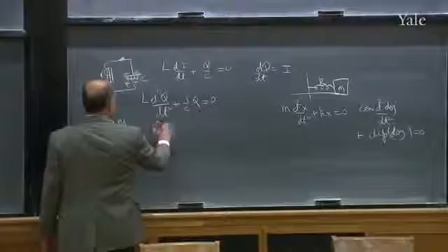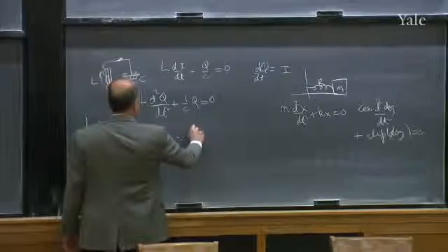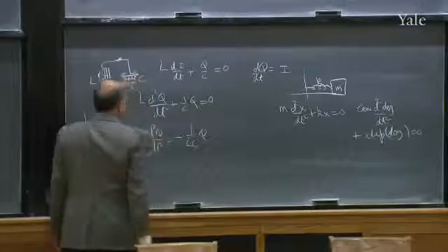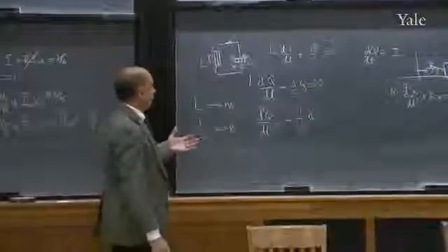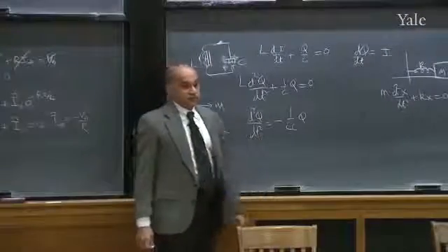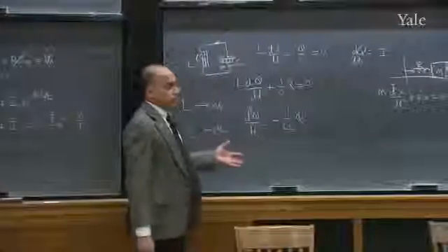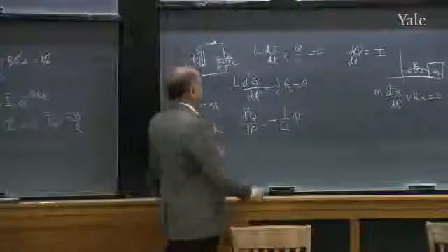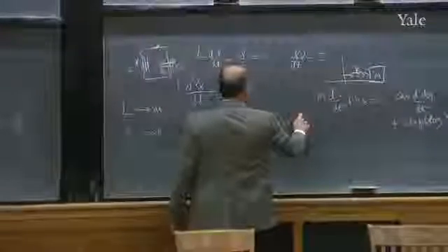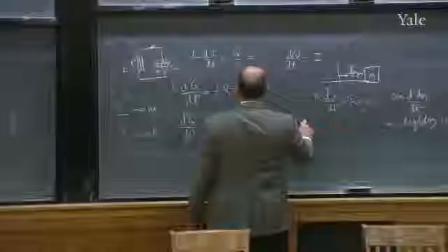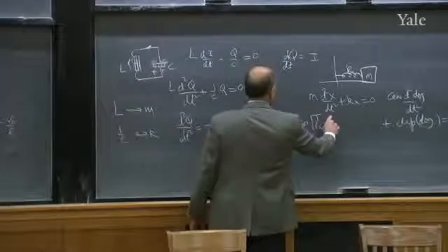Once again, it's a differential equation. You write d²Q/dt² is minus 1 over LC Q, and you're asking yourself, give me a function which, when I differentiate twice, looks like itself. There's always the exponential. There's also sines and cosines, and you can take any combination you like, and one acceptable solution is some constant A times cosine of square root of 1 over LC times t.